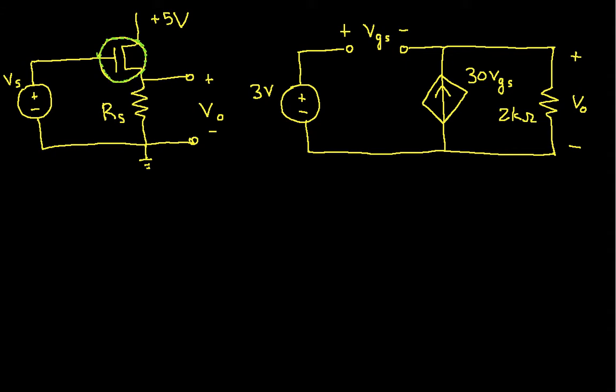And within the linear range, you can then look at differences between the nominal operating point and the actual currents and voltages in the MOSFET. These differences are called small signals. What you typically do then is use the MOSFET to amplify the small signals. There are ways of making that work, using coupling capacitors or other methods of coupling signals together, which are quite a bit beyond the scope of this video.